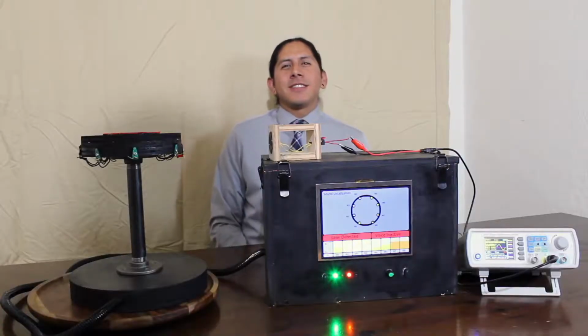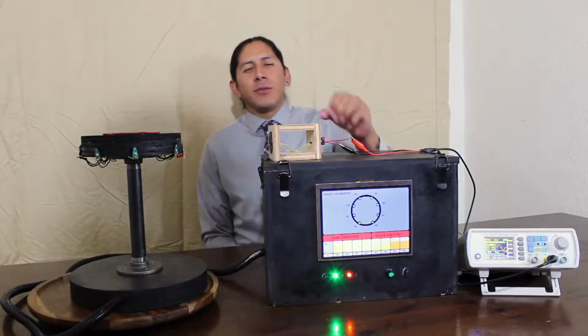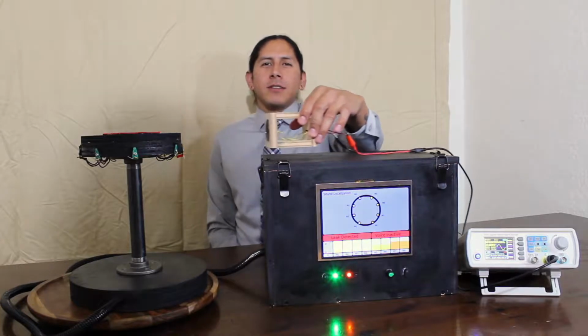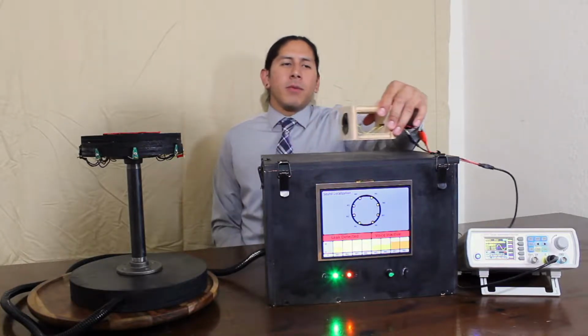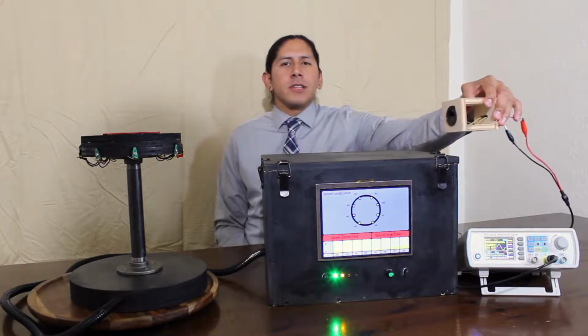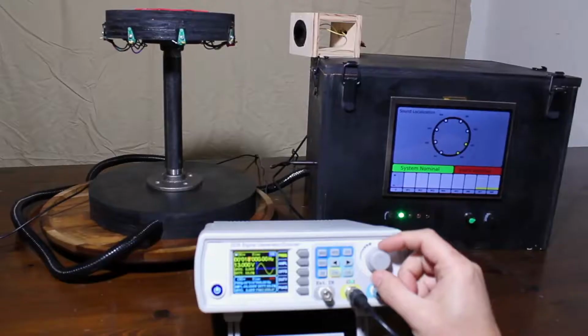The largest detection sensitivity of the system is around 24 kilohertz. At this frequency and of similar or greater magnitude, the detection range is about 1 centimeter to 70 centimeters. Past this distance, the source leak would need to be of greater magnitude.